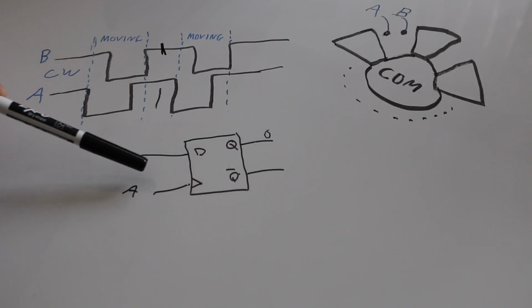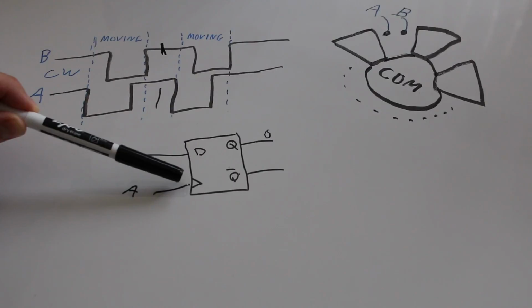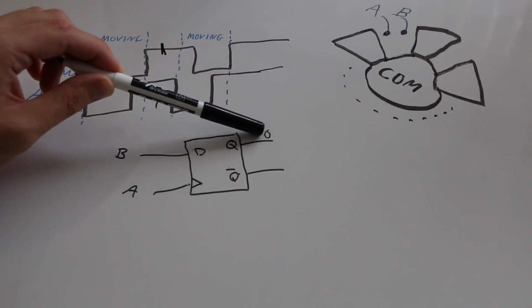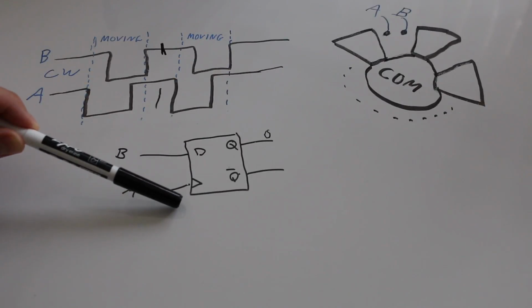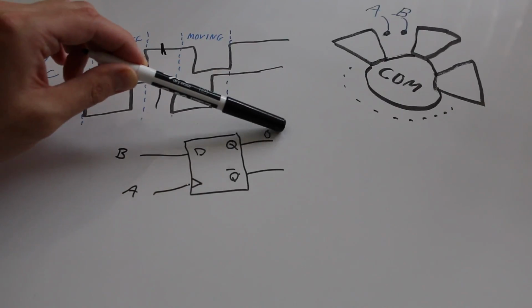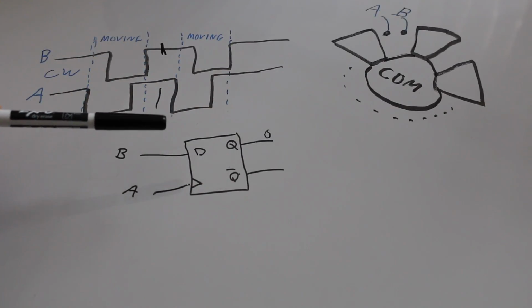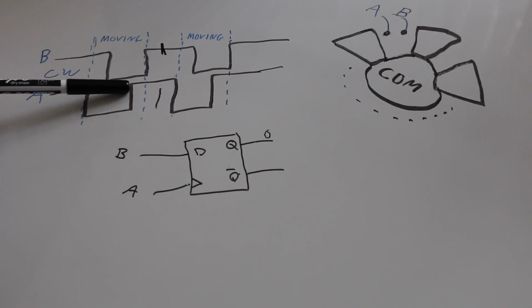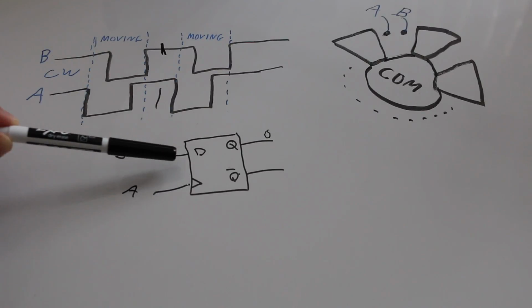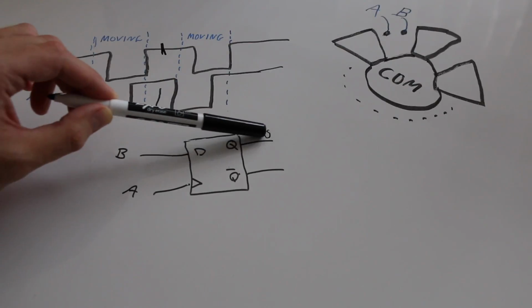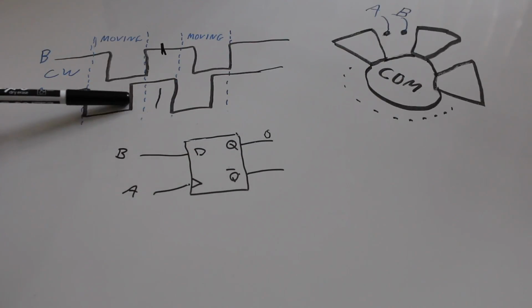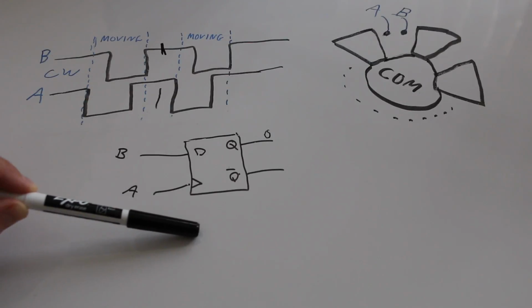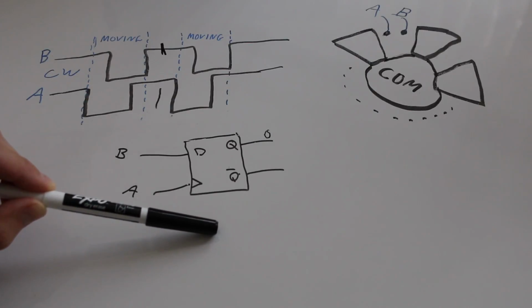And if you try to monitor the clock for rising edges to see when did this actually happen, so you can trigger another circuit when you get a clock rising edge, well, you're kind of in a race condition, because at the moment that this is going high, you are going to be starting to clock B out to Q, and at the same time, you see this rising edge, and your other circuit says, oh, there's new data.